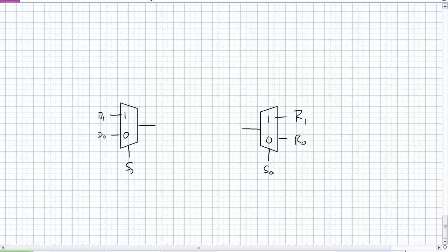Okay, so on the other end of this whole multiplex arrangement, which we haven't really even discussed yet, is the demultiplexer. And exactly like the multiplexer being a parallel to serial converter, what's a demultiplexer? It's a serial to parallel converter. It's got one input, i.e. the serial input, several parallel outputs, and select input to determine which one of those receiver outputs it's assigned to.